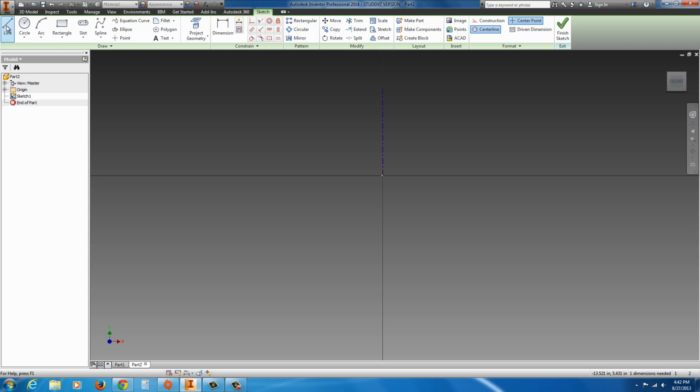The next thing we want to do is take the line tool and make sure you turn off center line, because you can't draw a profile with the center. Draw a line straight up, make it 2 inches, just type in 2 before you complete it. In this case, we're going to end up deleting this one anyway, but I'm just going to draw it out as such. And we're making a little under area here for the head of the bolt and close it. Hit escape, delete the line on the top, and now you can move these around.